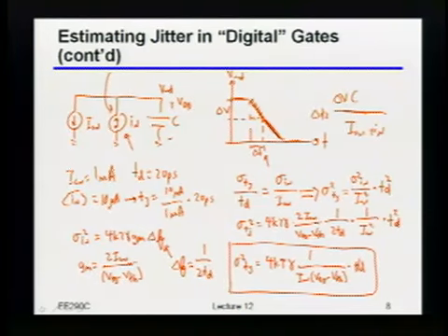Okay. Now, by the way, I mentioned that second method because if you start thinking about something like, for example, power supply noise, which would actually affect all of those inverters and has a certain spectrum associated with it, and if I have a long chain of those inverters, what I'm basically doing is indeed sinc filtering or box filtering the variations on the power supply. I again have to make some assumptions about uniformity or the overall supply variation to delay variation at the output, but that is actually a pretty powerful, or pretty reasonable, analysis technique.